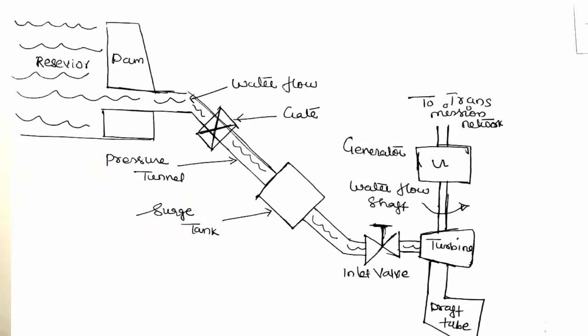All these are details in the mechanical side, and it would be difficult to cover that as part of this series. But again, there could be a single nozzle or multiple nozzles, and the water which is leaving goes to the outflow, or tail race. There could also be a draft tube provided, in such a way as to increase the pressure of the water leaving towards the tail race, to provide a smooth outflow.